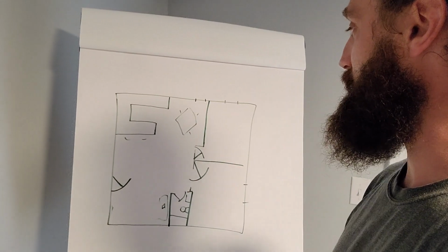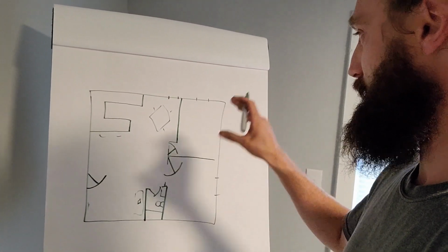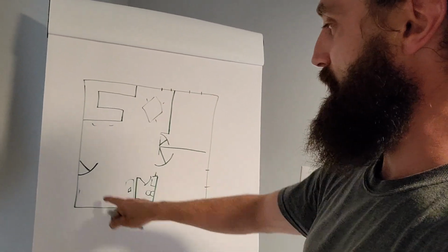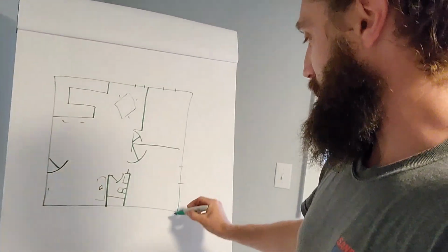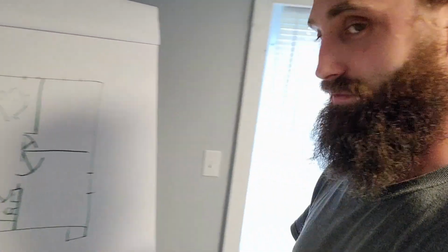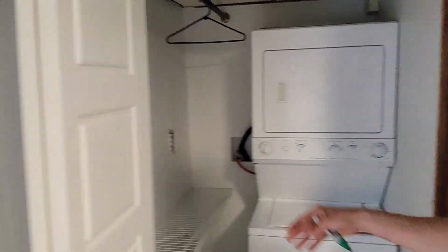But yeah, here I'm looking at the kitchen, okay? You want to get a rough idea of where the cabinets are. And I like to take a really good look at the kitchen. Kitchens are kind of difficult because there's a huge cooling load in kitchens, and a lot of times we have a hard time figuring out where we can physically put enough air volume in registers to make it work. So be as detailed as you can when it comes to kitchens, laundry areas, these high load areas, because we need to know.